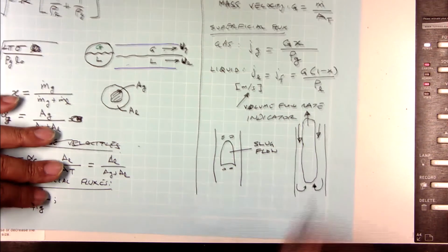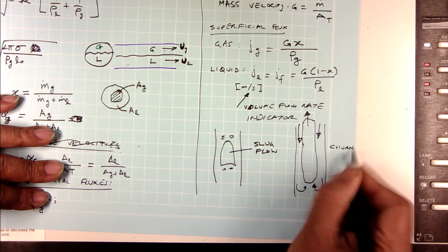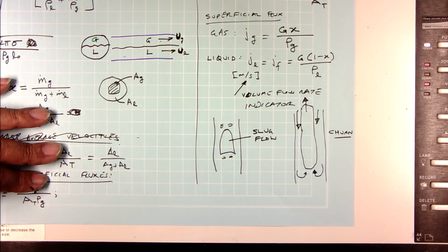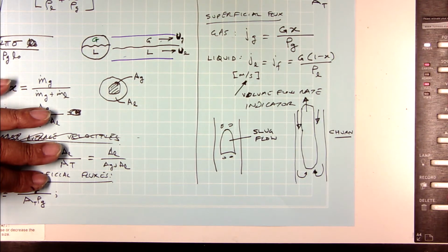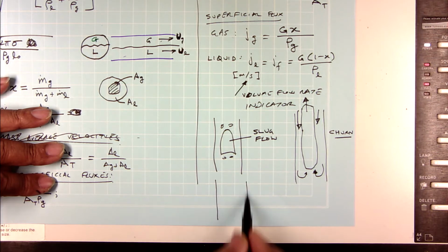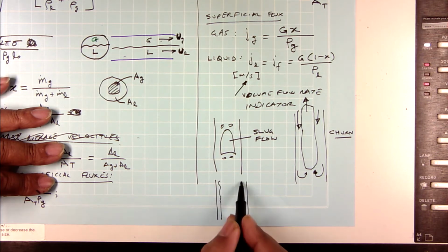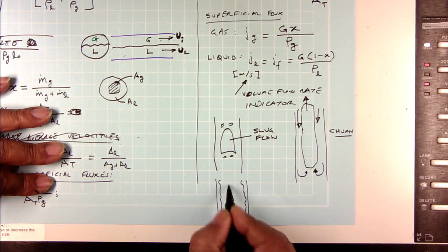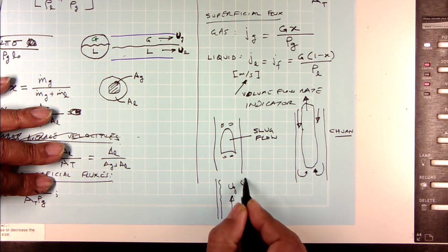Okay. And so, then you have churn flow, and the problem with churn flow is you get localized areas of flow reversal. Okay. And then if these churns start joining up at really high vapor velocities or gas velocities, or at really high values of mass fraction, then you end up with what is known as annular flow, where the liquid is on the edge and the core of the flow is gas.